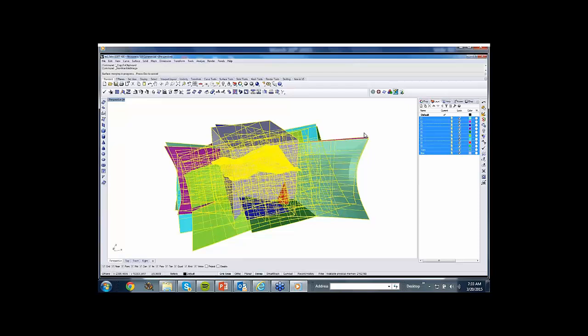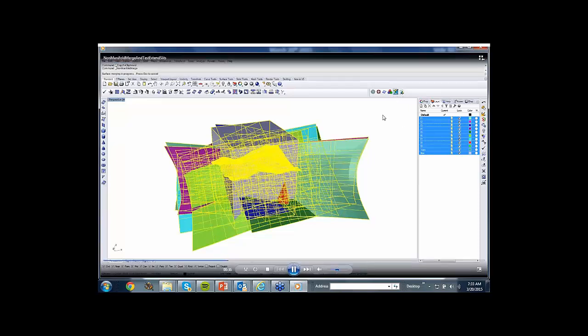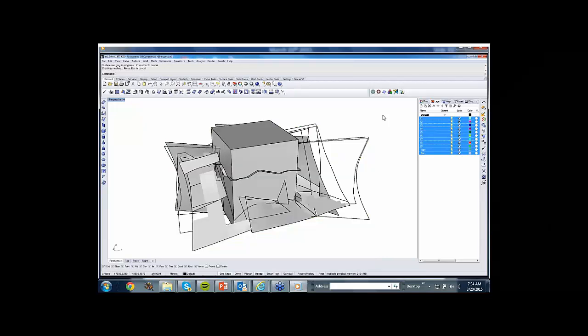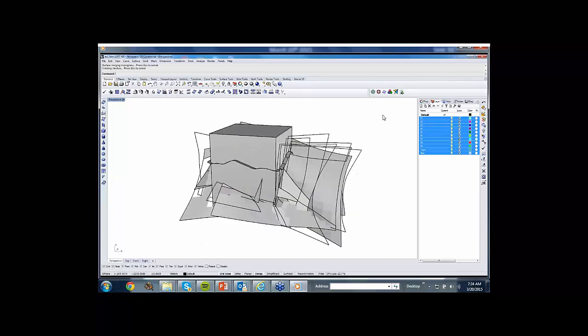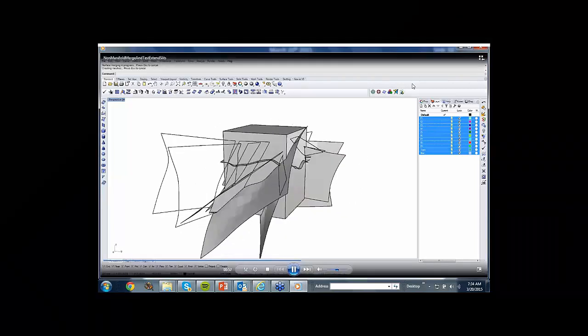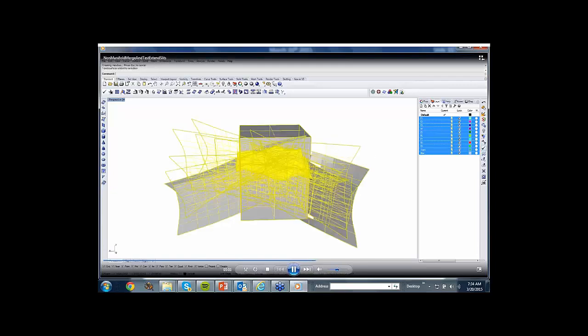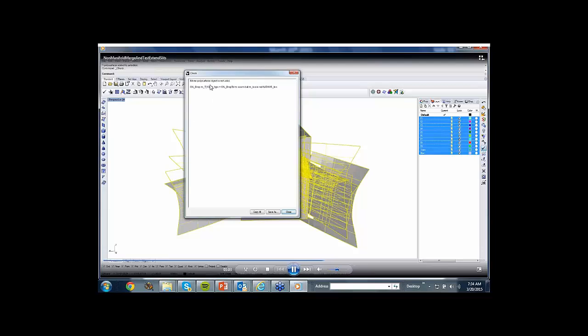And then I clicked on the command. The old icon for merge breps now uses the non-manifold merge command, which is a gift from heaven, because what it does is that it produces a really, at first, very ugly, but later on very pretty non-manifold surface that can be meshed with very few problems. So look at this shape now, what it looks like. It looks a little bit decrepit. Some parts of it are transparent, some parts of it are opaque.